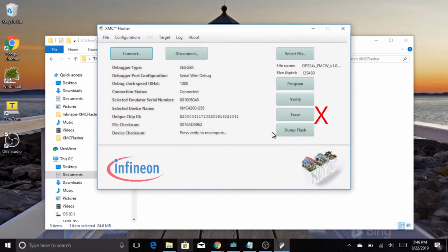Do not press the Erase button, as OmniPreSense saves factory settings in some sensors. Pressing the Erase button will clear those out, as well as any persistent memory settings which have been saved.